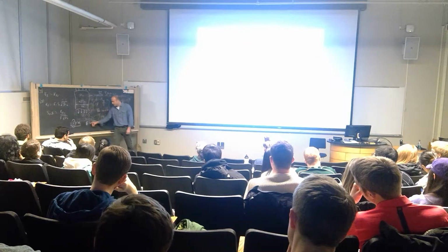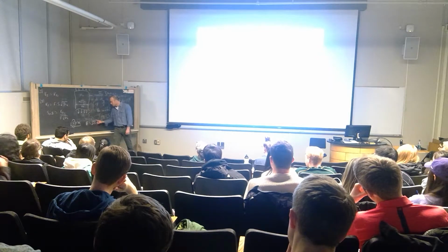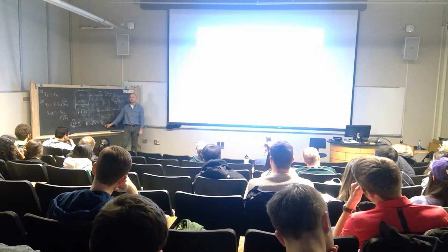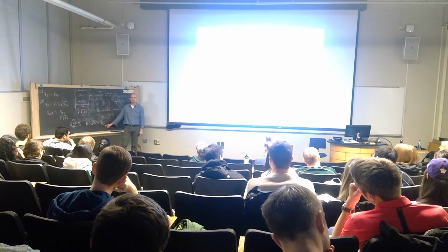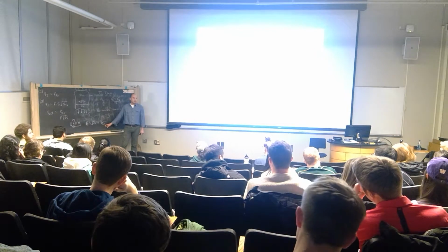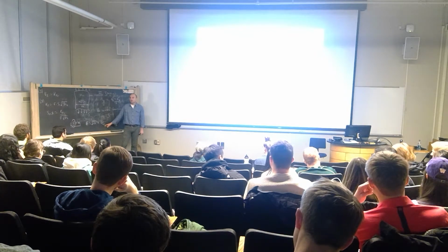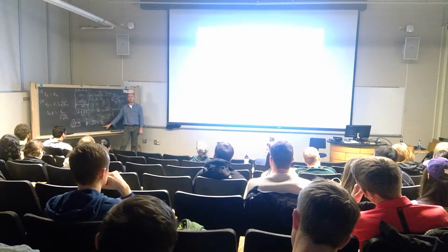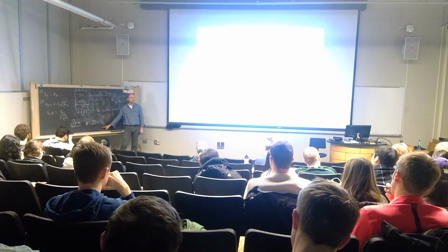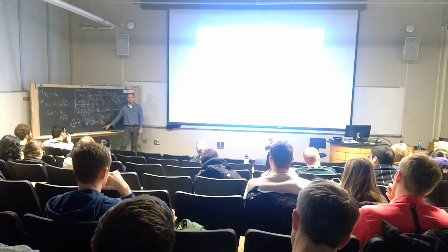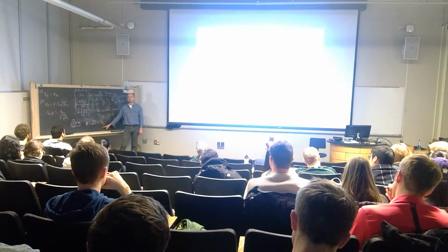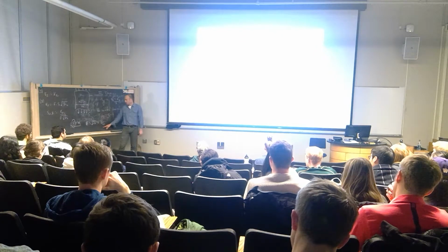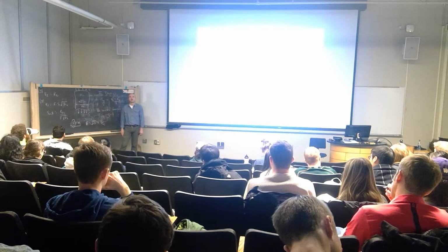Go back, I check my numbers: stress again, flaw length again, calculations, and I think I find again a value of K1C that's lower than what I expected. Then either the material is different, so I go back and check the chemistry of the material, or I go back and find out what environmental conditions could have caused that fracture toughness to change. Could it have decreased? Can we have fracture toughnesses that change? They could, right? So I start looking at conditions that do exactly that.